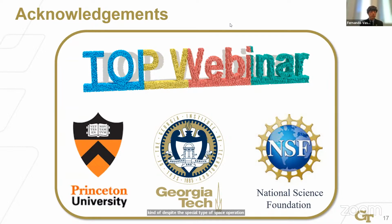And there have been some people that have been able to use self-assembly materials to obtain a kind of spinodal microstructure without actually 3D manufacturing. I think it was Carlos Botello from MIT. He mentioned that he was working on that and he was able to obtain some quite interesting results. But for now, I understand they are limited to isotropic materials. And that's another thing. Not only can it be hard to control exactly the properties with the spinodal decomposition, but it can also be very hard to change from one type of spinodal class in one point to another type of spinodal class in another point in the material.